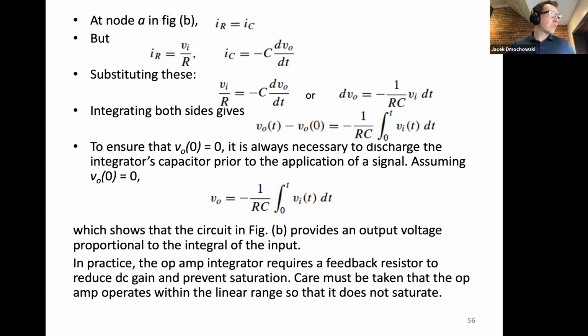The other thing you have to pay attention to is that this integral should not exceed your power supply voltage, because otherwise you'll be asking your op amp to produce a voltage that it cannot physically generate. So you have to make sure that you do not saturate the op amp. If your power supply is, I don't know, plus or minus 5 volts, you can't ask it to produce an output of 20 volts, for example. Alrighty.